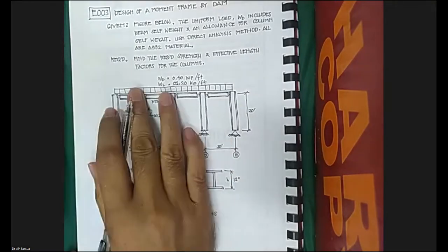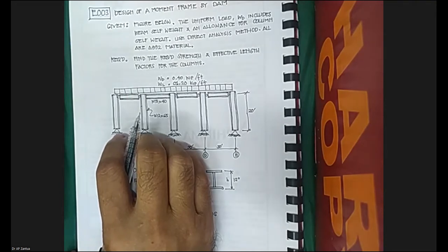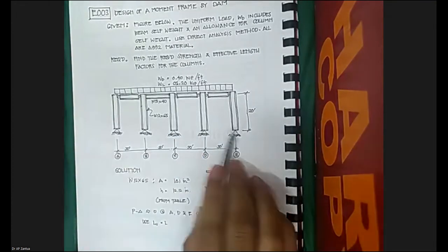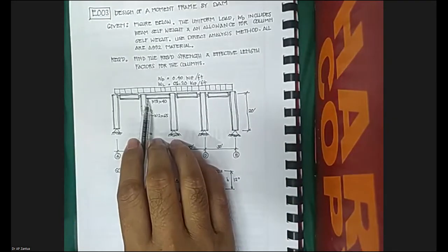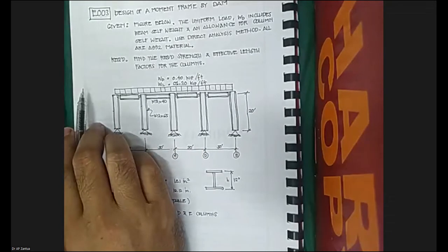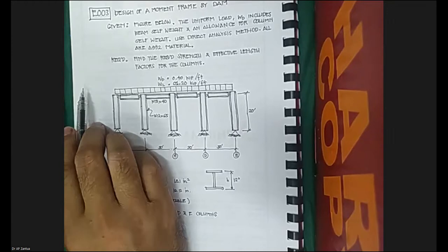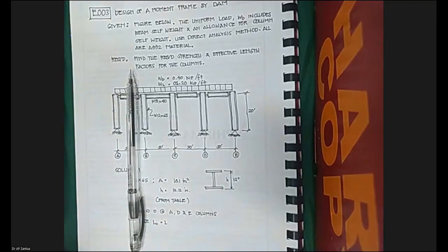The interior frame at grid line from A to E could be modeled, because the whole frame will resist moment because of this fixed connection, in which the stability loads from three leaning columns are combined into a single representative column. So for simplicity, we can combine A, D, and E. Because of that, we have the following: